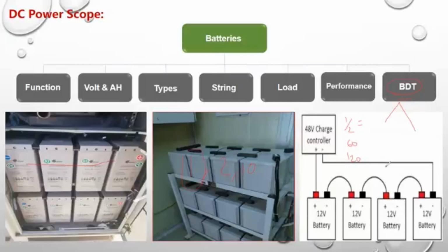Now, here you come with something called an avometer. You set it on the DC volt and then put one probe on the positive and the other on the negative. And start to see the number on the screen of the avometer and start recording your measurements. This is all the story of the batteries and their numbers and what they're used in.